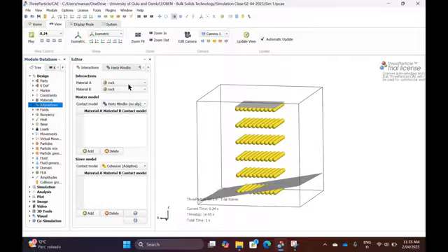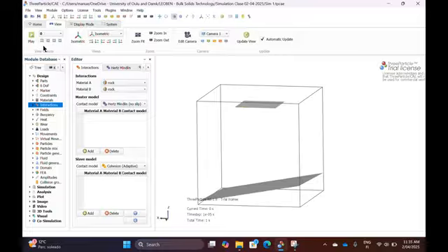One minor thing here. I just changed something in the current time step. Not a good idea, right? Because I'm at 0.4 seconds. I actually need to go back to the very beginning and define it here. So from the very start, at second zero, I need to define that there should be a contact between rock and steel.